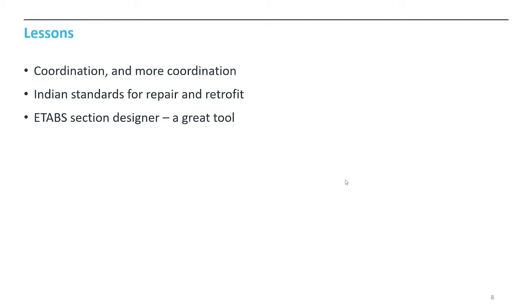And we found out that section designer is a great tool. In the very beginning of the design of strengthening, we decided to use section designers for all the columns which we are strengthening. It took a lot of time to build and place those additional rebars exactly, not only the new rebars which we were proposing, but additional rebars as well. But once it was ready, we found it very handy.